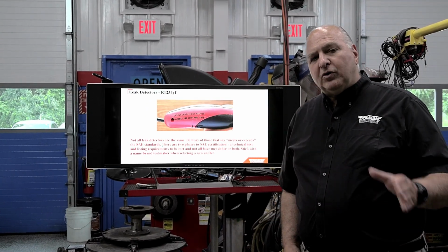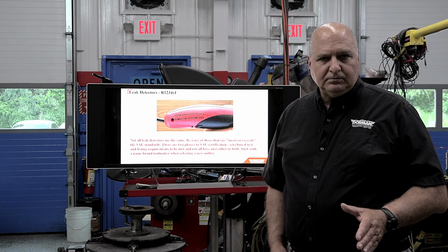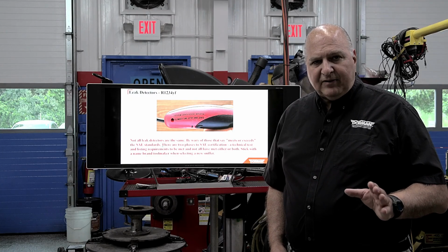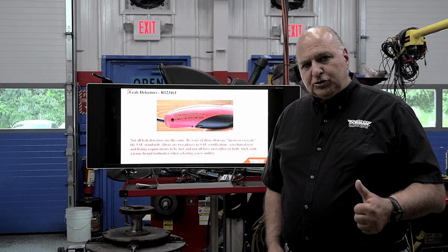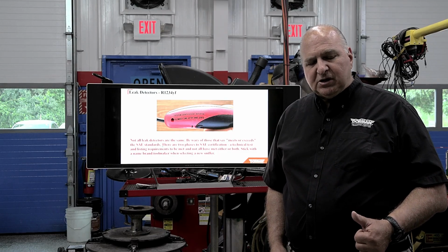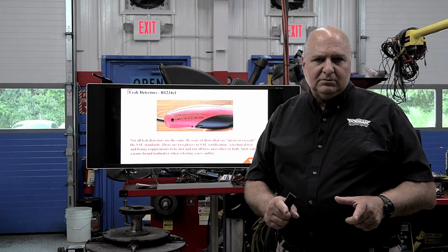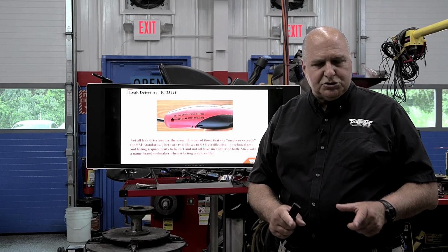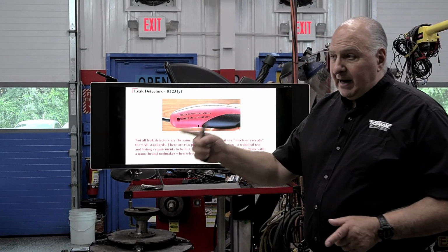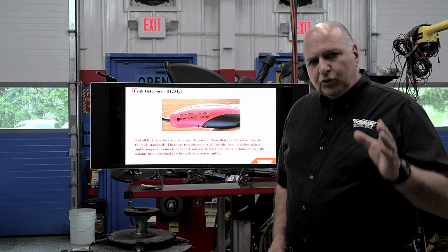Usually when we recover all the refrigerant and put CO2 in, we do the same test with CO2. And don't forget about going up the drip tube. If there's no water leaking out of it, make sure it's pretty dry. We put the CO2 sniffer there and see if anything's leaking out. Once we're done with the CO2 that's in the system, we remove the CO2. You do not put it in your machine. Please do not recover it in your machine. You recover only refrigerant in your machine. Okay? And again, anything with an identifier built in will only allow you to pull in 1234yf.